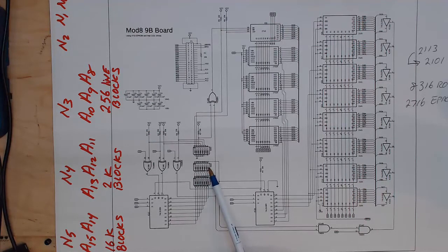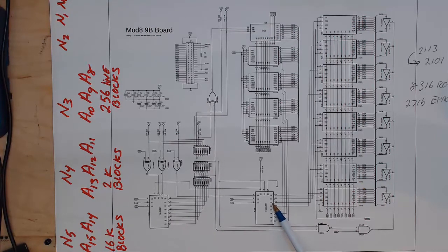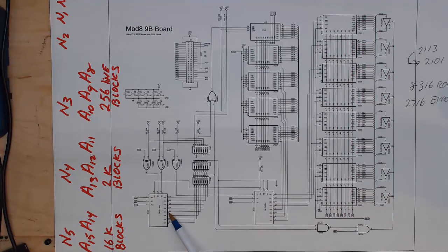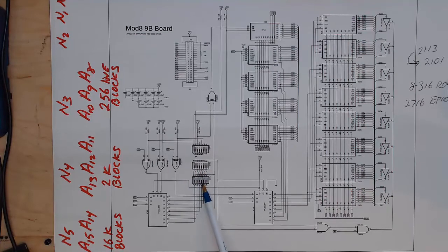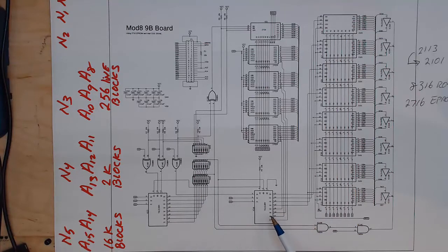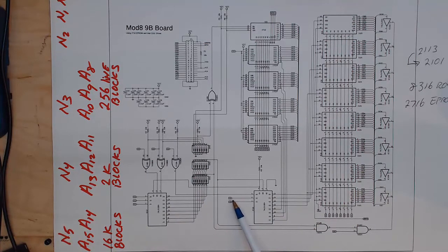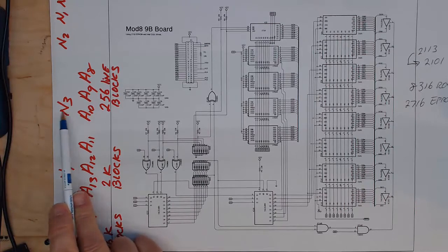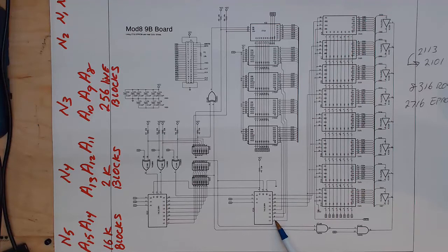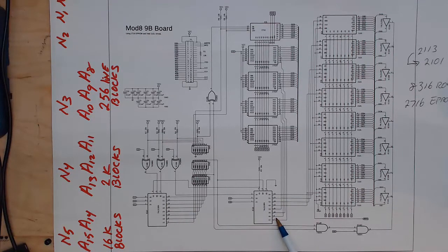If we had two of these on at a time, then we would have wraparound and our memory would be selected twice. We could select it at one address, for example, at 0, and then we could select it again if we put an address out at 4 to select output 4. So typically that's not what we want. We typically would only want to have one of these low at a time, so we can use that memory space for something else. Then we have another 74138 that's using addresses 8, 9, and 10, and we can see that's just N3. So this 74138 is creating 8 256 line memory blocks.